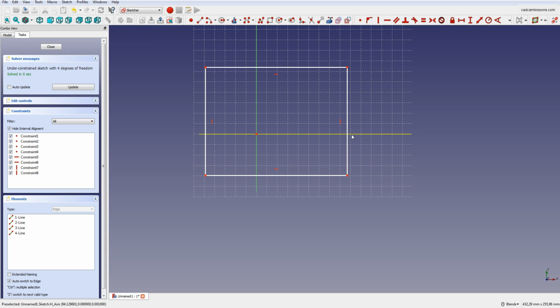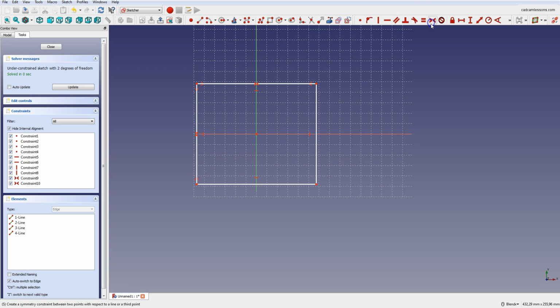After creating the first solid, we will discuss some navigation methods, some basics, how to rotate, how to zoom. But let's get back to our drawing. We have a sketch, but it is not oriented to the origin of the coordinate system and it is not dimensioned. At the beginning we set the sketch symmetrically to the XY axis. With the Ctrl key pressed, select two vertices and the axis and select Symmetry Constraint. OK. Repeat this for these vertices and the x-axis, and again. OK.